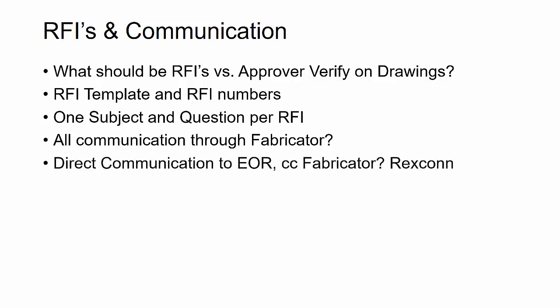Then, if you have any phone calls, sometimes it's faster to just pick up the phone and say, hey, can I get this clarified real quick, and can we just take a look at the design and get something answered, versus having to write extensive RFIs. Usually what I'll do is if we have a weekly call with the fabricator and we're getting clarifications, you then follow up with a written summary that will be a record of conversation, and you keep a log and assign a number to that.